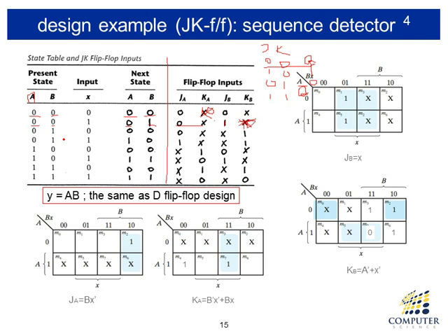In this way, you can extend the truth table. So let's pick up a few more cases. Here, for flip-flop B, 1 is the current value, and the next value is a 1 again. So to make from 1 to 1 on the next clock tick, the possible inputs for JK are 1 and 1, or we can have 0 and 0 so that the value remains unchanged.